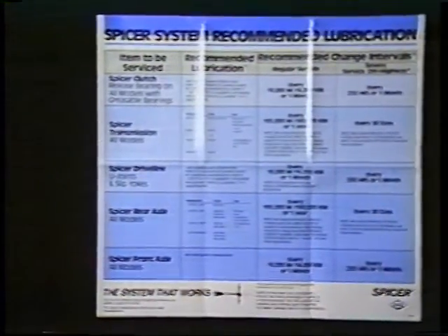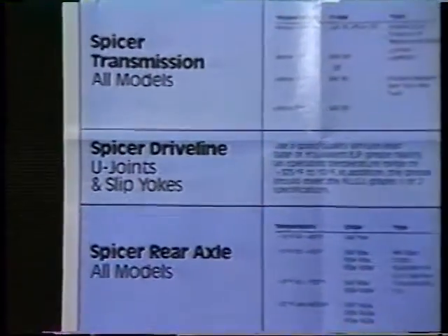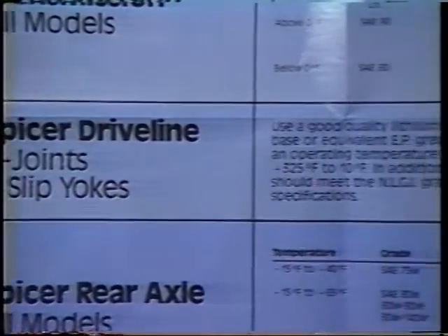I understand all that, but I have a few questions. How do I know what kind of lube I should be using with my equipment? And how often does it need to be changed? I would check your Spicer lube chart. This should tell you the exact type of lube needed for a specific part. The chart also explains the lube cycles you should follow.